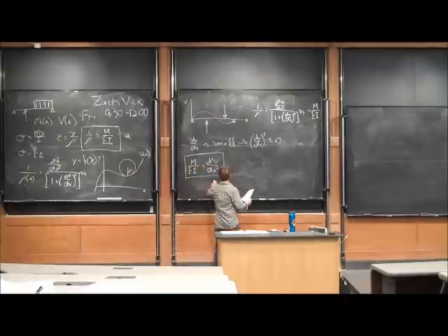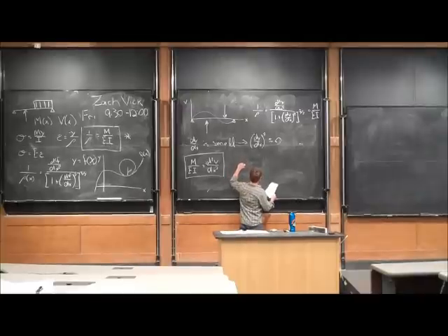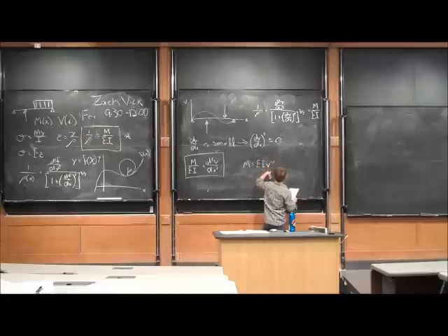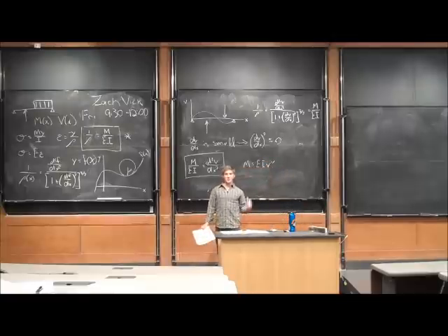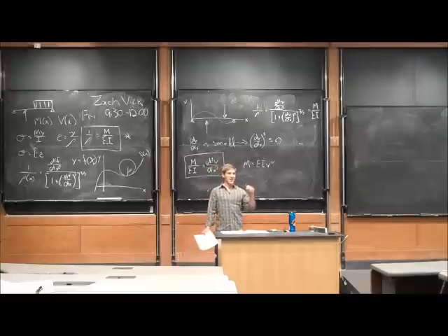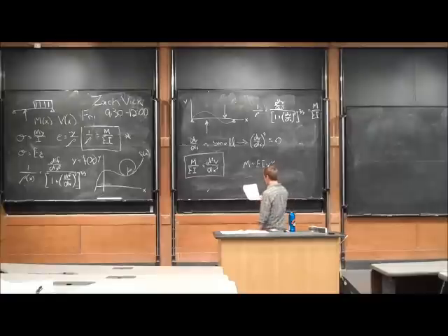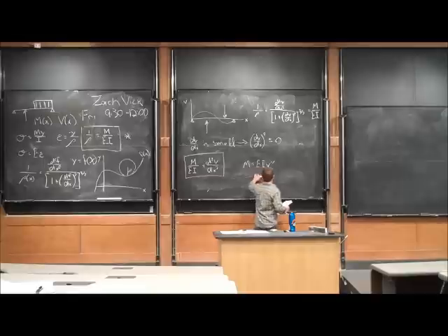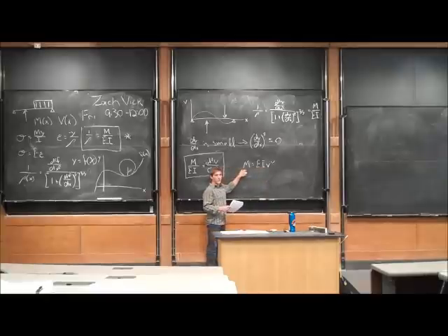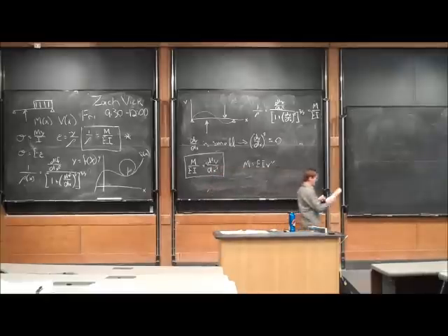So this is often simplified, and an easier way to write it is M = EI v double prime. You'll remember from Dynamics that a lot of times you'll use a prime as a derivative with respect to x, and a dot as a derivative with respect to time. So that's just an easier way to write it, and we'll use that for the remainder of this lecture. So if v is the deflection, what can we say about v prime or v double prime? Well, v double prime is directly proportional to the moment seen in the beam. But if we want to look at v prime,